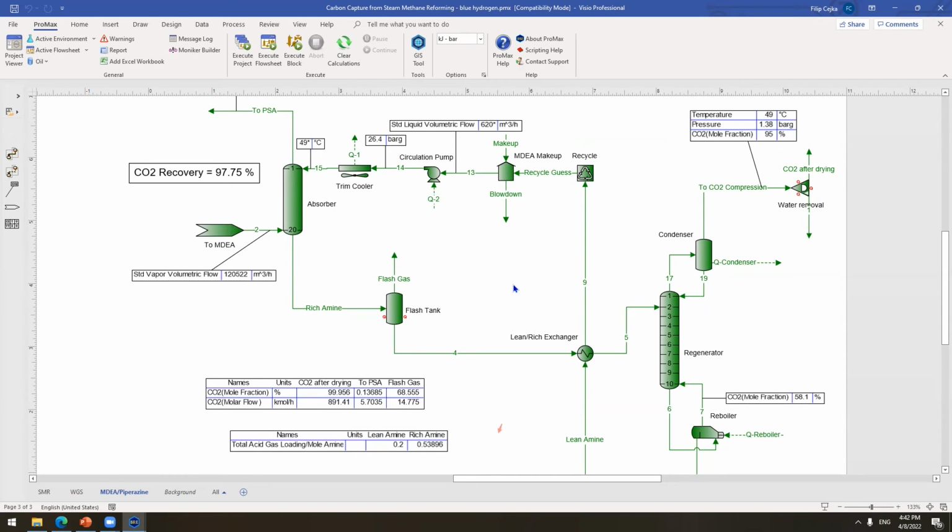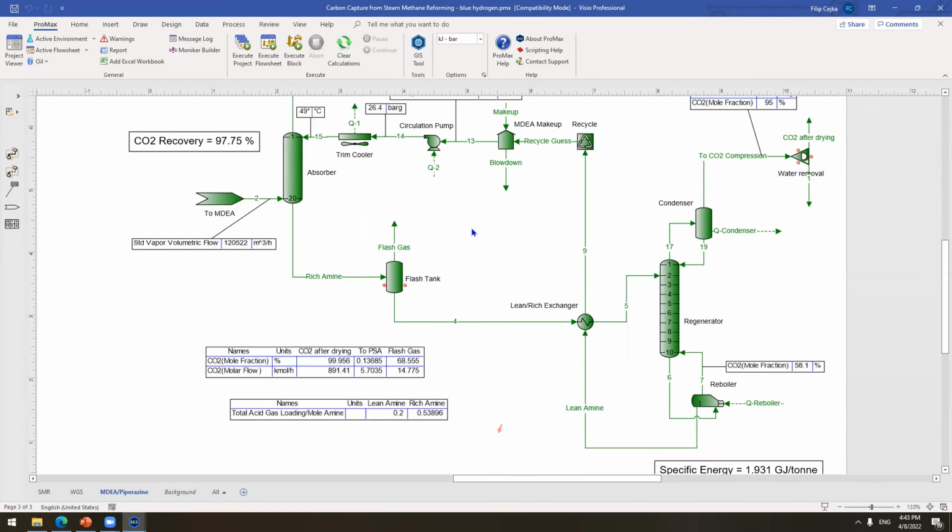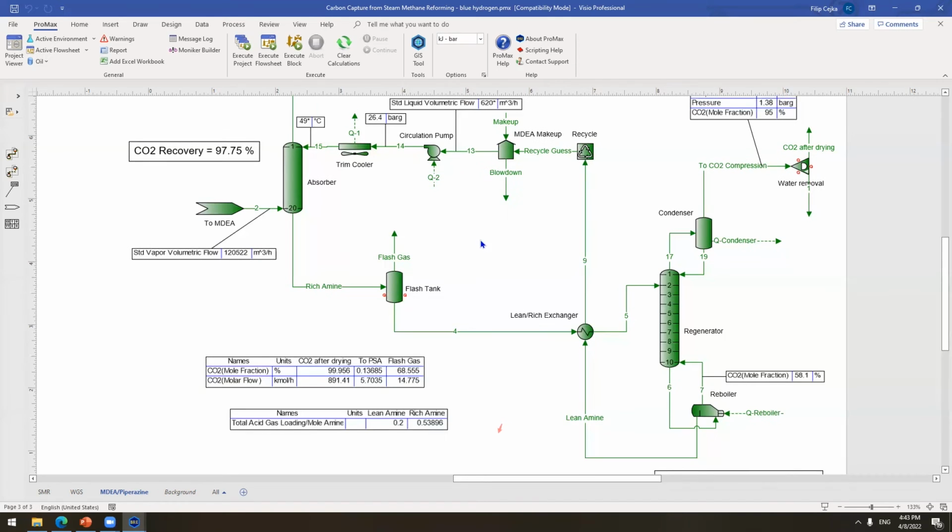Always you need to have some specifications, and then you try to achieve, okay, can I reduce, let's say, the flow of my amine? That means I'm going to have less amine, but what's going to be my fraction flooding, right? Or if I'm going to use less concentrated amine, how is it going to affect the reboiler duty? So there are a lot of trade-offs in here.